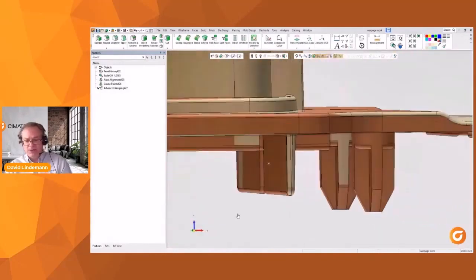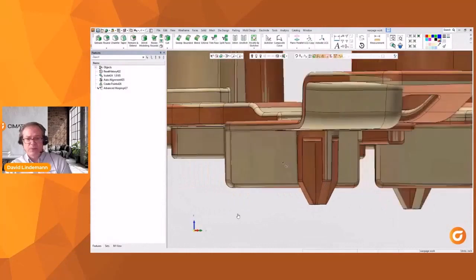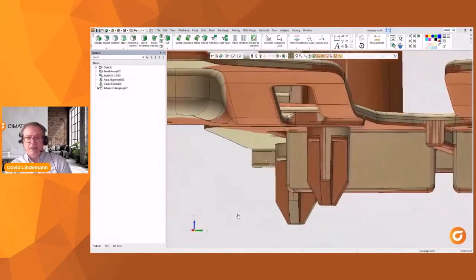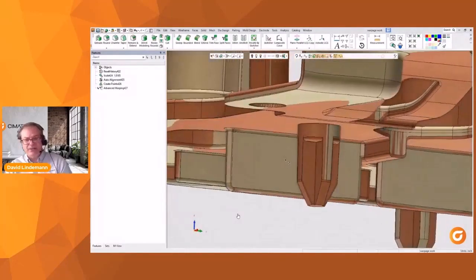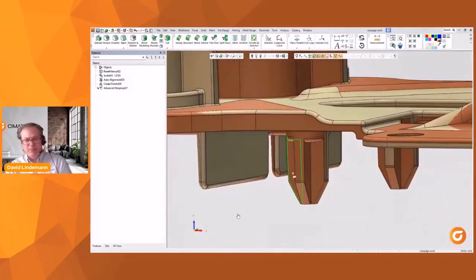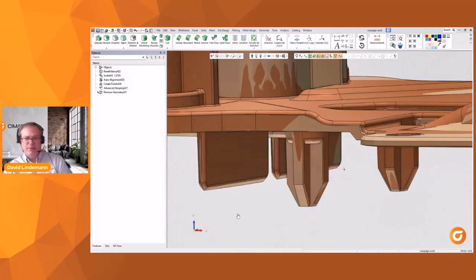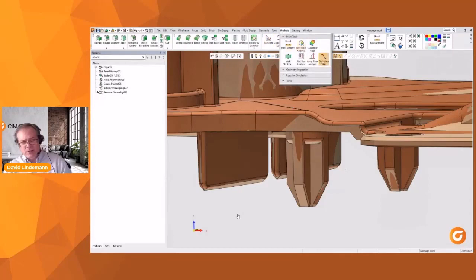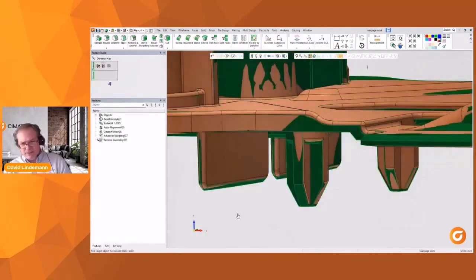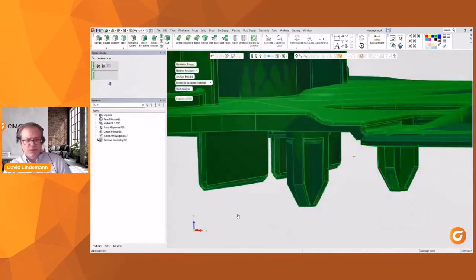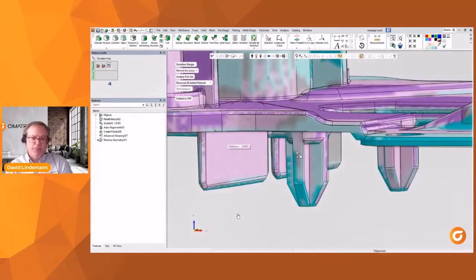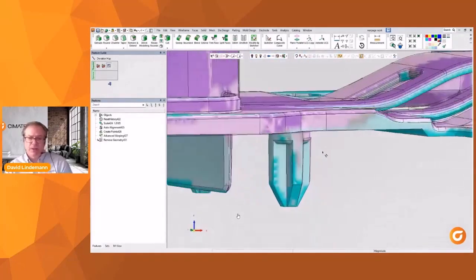All right, we knew that the bosses down on the other side, the core side, were definitely out. And now looking at them, I might wonder, are they straight? I probably want to touch that up a bit. Also, the location looks like they've stepped out a bit. So if I've already tooled this, and I want to replace my cavity insert here, I still would want to measure up to right where that ejector pin location is. So let's say I put an ejector pin at the bottom of that boss. That's what we want to address.